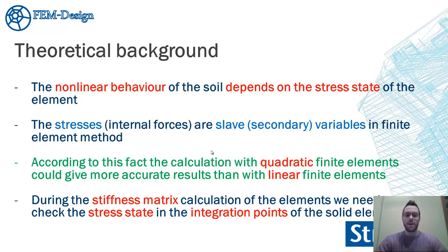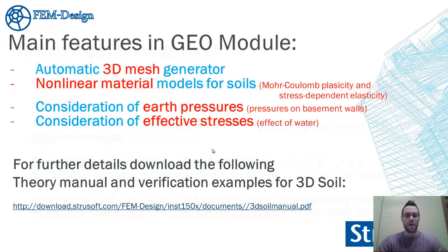So during the calculation and during the stiffness matrix calculation of the elements, we need to check the stress state in the integration points of the solid elements. So it is a very important thing that the calculation according to the numerical integration is based on the stress state in the integration points of the solid elements.